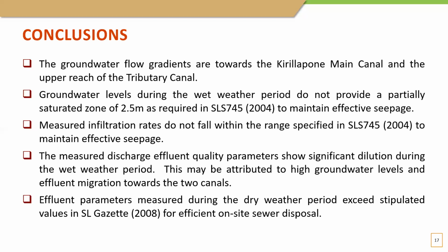Next, measured infiltration rates do not fall in the range specified in SLS 745:2004 to maintain effective seepage. The measured discharge effluent quality parameters show significant dilution during the wet weather period. This may be attributed to the high groundwater levels and the effluent migration towards the 2 canals. Effluent parameters measured during the dry weather period exceeded stipulated values in the SL Gazette 2008 for effluent in on-site sewage disposal. These are the conclusions I have made from my